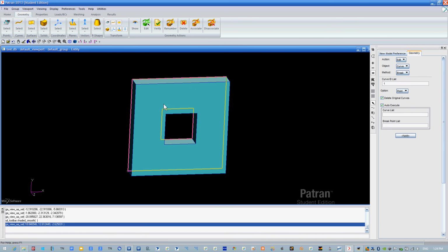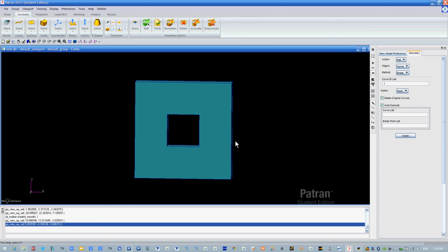Yeah. So these four corners, we need to prepare them. Even if you're going to do an extremely minute fillet, you need to add it. Not only does this actually increase the mechanical strength, if you were to build this in real life, you'd increase the mechanical strength by doing this. So there's actually real reasons for doing it, but as far as the analysis goes, it's almost necessary.